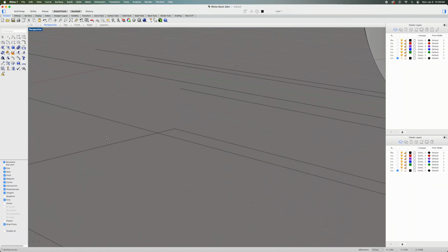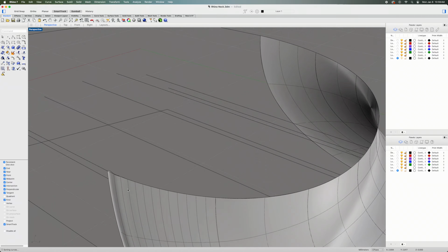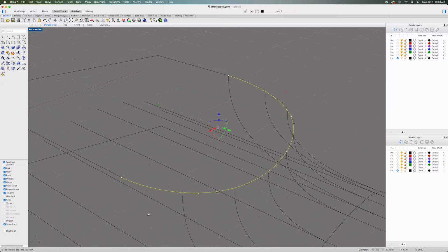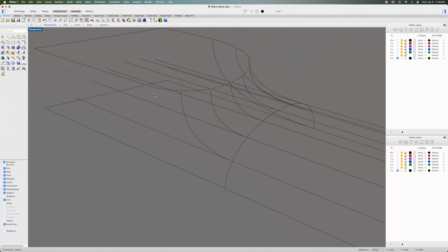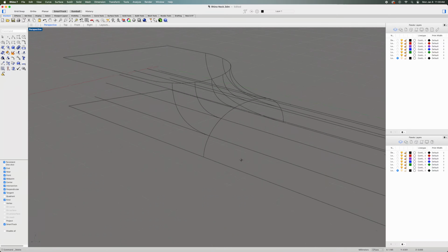But if you look closely, you'll see that there's a funky little curl going on. That's what happens when there are 2 points, or if a point isn't lined up correctly with the segment. So what I have to do is select one of those extra curves that I don't need, and delete it. Then I'll redraw. I'll go to the other side first, and I'll see if it's the same issue there, which it is. And I'll delete the extra curve point.